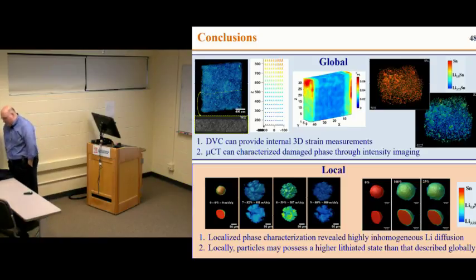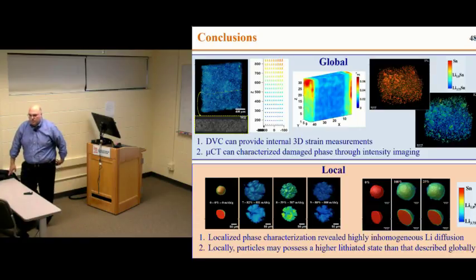I noticed that there's still some restriction regarding the size of the sample to take the measurements. I mean, while you're loading, you have to keep it constant. Keep what constant? The load. You mentioned that you apply the load and keep it there while you take the measurements. Yes, actually, the application is displacement, right? So the displacement is held constant. The load drops a little bit. We were worried it would drop a lot, meaning it would relax a lot. It's a polymer, right? It's viscoelastic. But it doesn't relax a lot. It relaxes a little. But anyway, it's the displacement that is held constant, not the load.